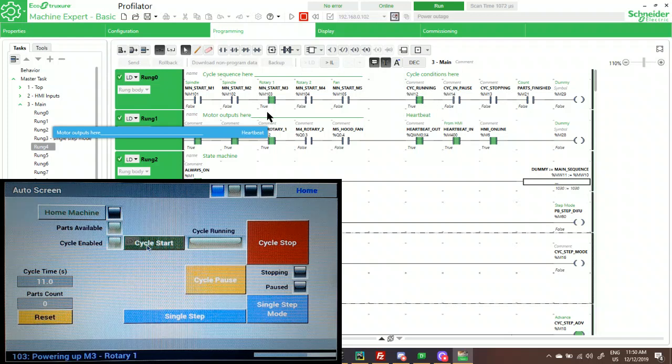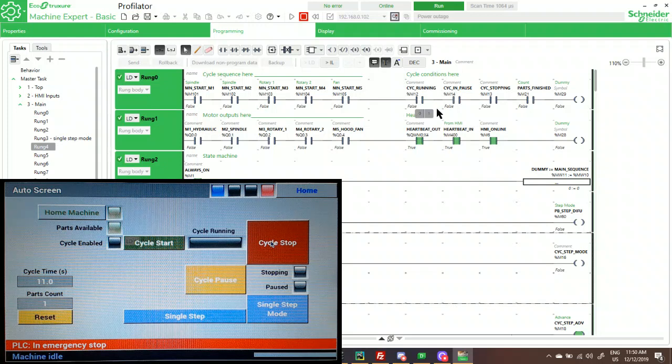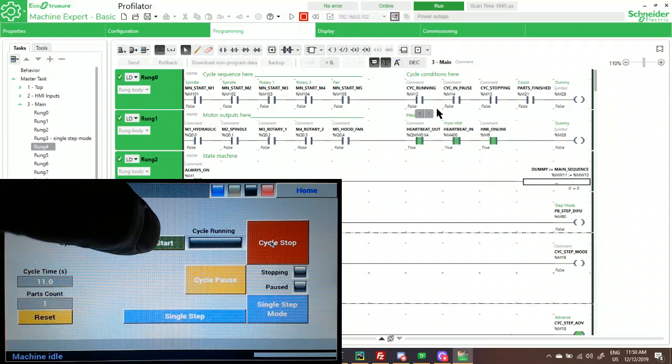There's one more thing I wanted to look at while we're here, and that is emergency stop. I have it set up currently for what I call a double break. The program is requesting a cycle stop, to hit the cycle stop button in order to break it, which I will do. And you can see in the background the cycle did break. It may be the client wants to break cycle immediately on e-stop. That's a simple fix in the program. So we'll give it back its ability to run, and here we go.